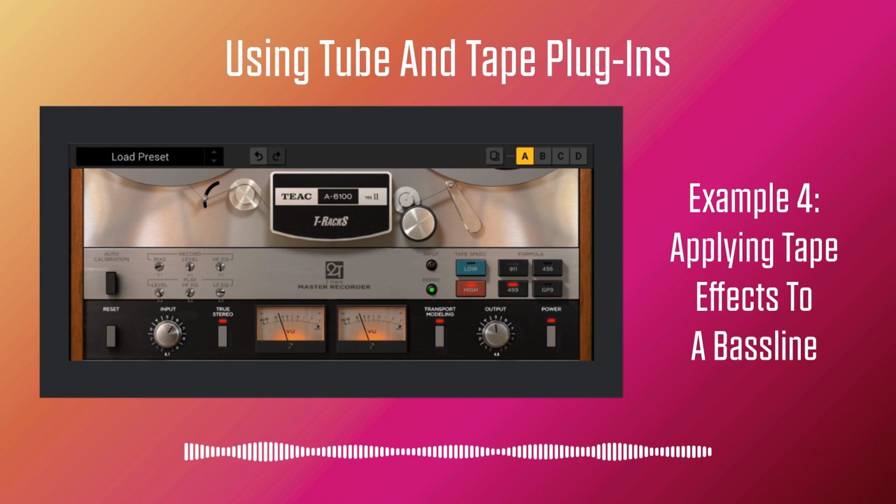I always start with the bias setting. Bias is used to reduce overall distortion levels. A low bias setting will result in more distortion, and a higher bias setting will result in less distortion. But that's not the end of it. Intentionally overbiasing is a common technique used to produce a gently saturated sound, resulting in a rounder and warmer response. Underbiasing can also be used to smooth out high frequencies and add distortion to low frequencies. The effect is very context driven, so play around until you achieve the color you're after.